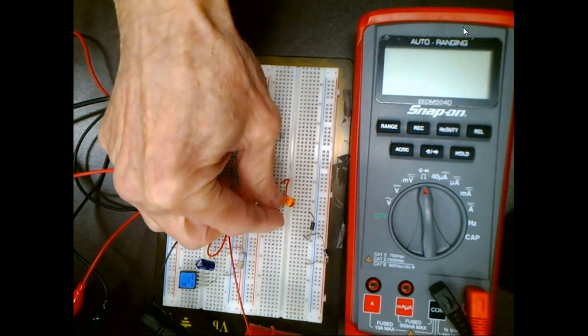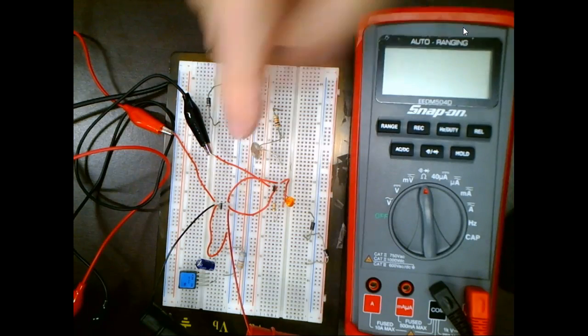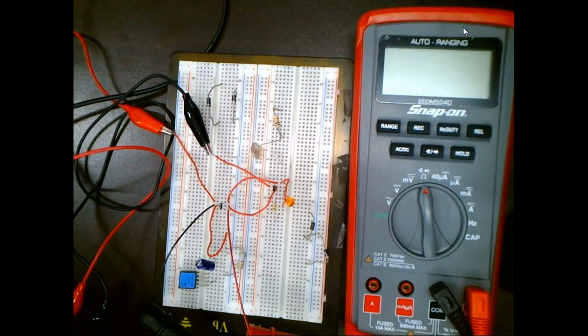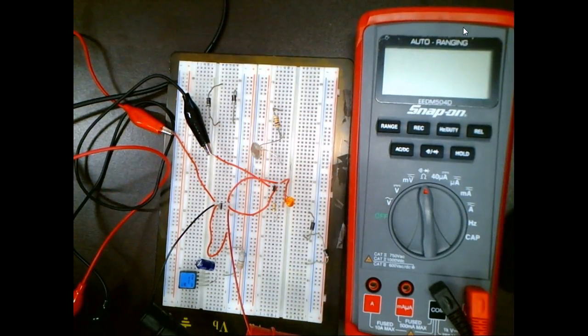This is a resistor. Now we can't put an LED in the circuit by itself normally, because I'm putting 5 volts on it. A diode only lets current flow in one direction, but we don't use LEDs for doing that. We use LEDs to create light. But LEDs drop about 2 volts. Anything over 2 volts is considered a short. So I'm putting 5 volts on it, right? You understand? So what I had to do is size a resistor that would drop 3 volts, and then the LED comes on. You already know that. You just had that.